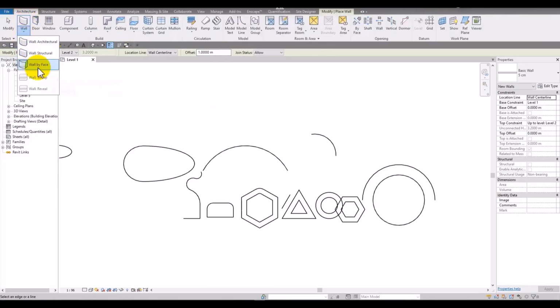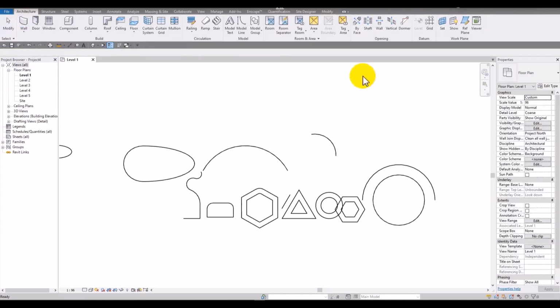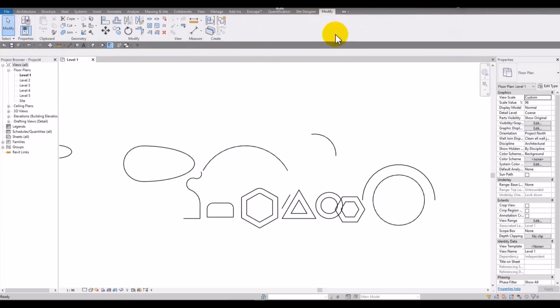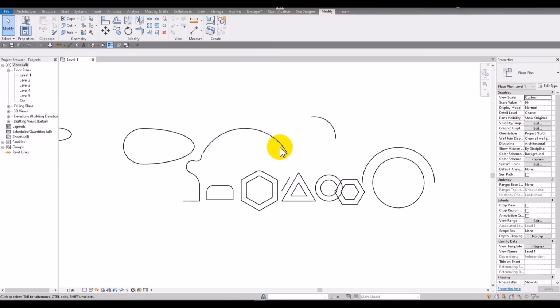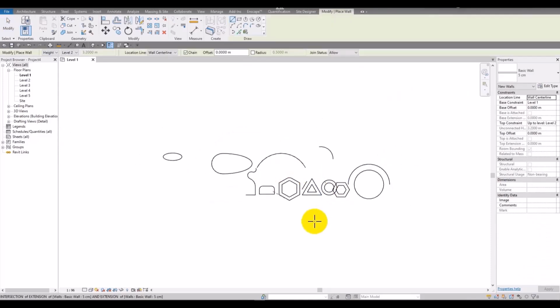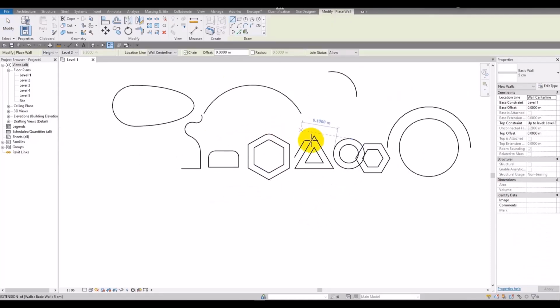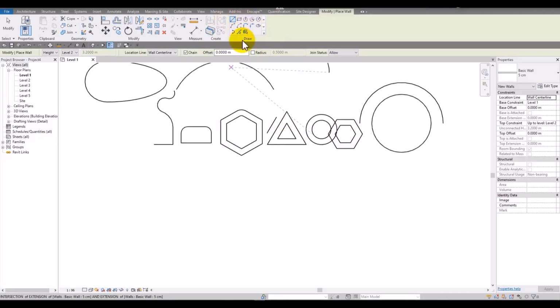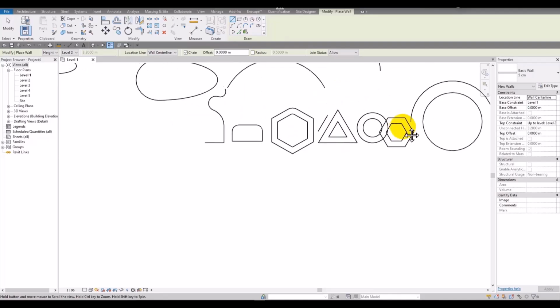Pick face, or here in this section, wall by face. Both are the same. Later, when you create a shape or volume without any special shape, plan or view, you can use that face as the reference. Then it changes it to a wall. Okay, we talked about the different types of drawing the walls.